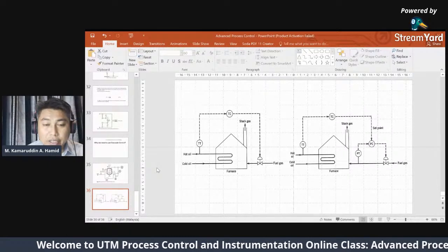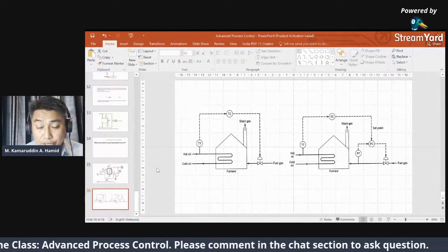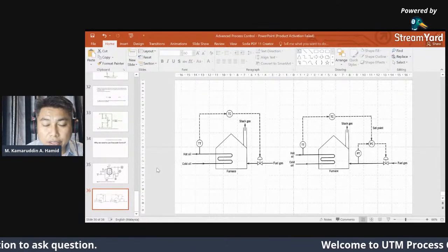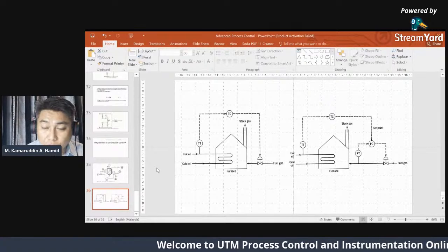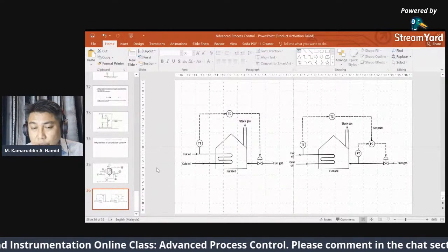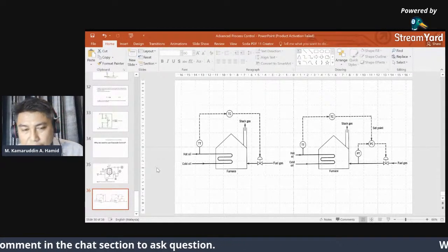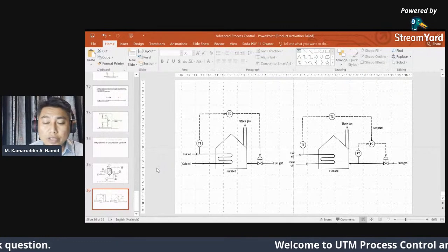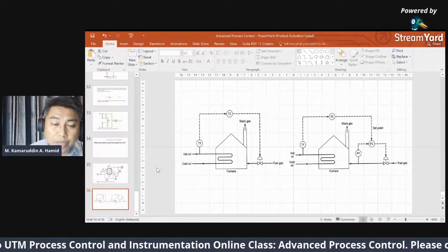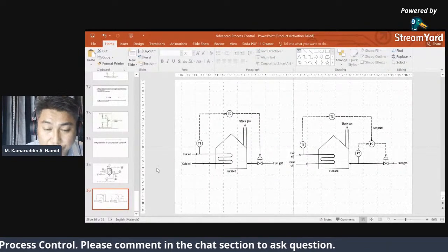All right. So for cascade control, you want to use it if there is a significant impact of the disturbance on your process. And how to do that? You stabilize the disturbance first by having another feedback control there. So cascade control is basically two different feedback controllers. You stack them together. Stabilize the disturbance, and after that, once the disturbance is stabilized, then you can control the primary control variable, which in this case is the hot oil temperature.